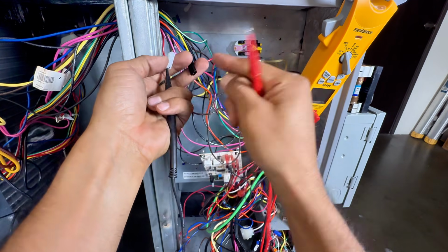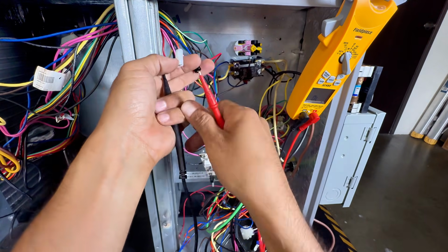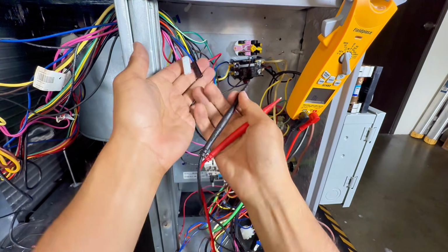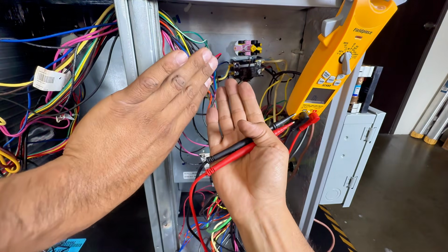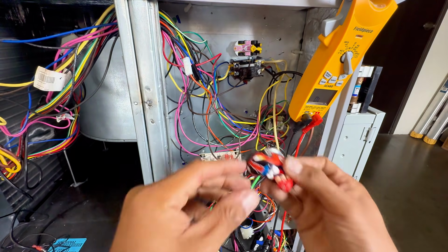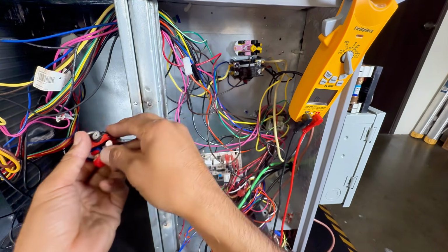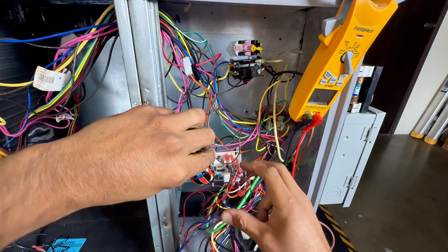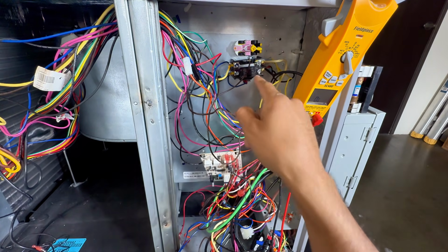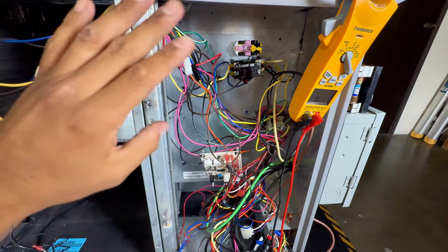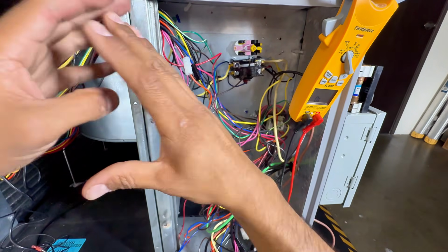So the meter sends a little bit of current going through, and it's able to make it back because all my pressure switches were closed. This is another way you can find out if all my pressure switches are good. So when Mario goes through, he's going to be able to come back to my board, which then sends 24 volts to that contactor coil that turns on the compressor. My reversing valve already has Luigi and Rosalinda. They already have 24 volts. And then I have a call for cooling.